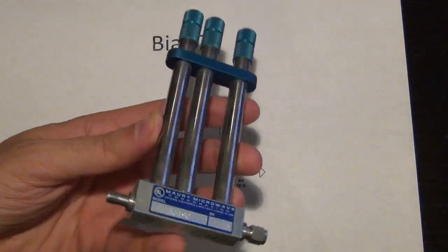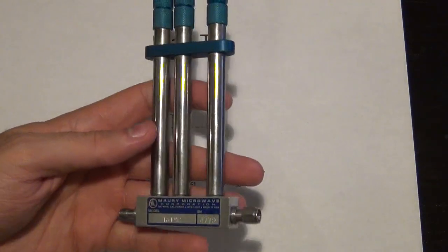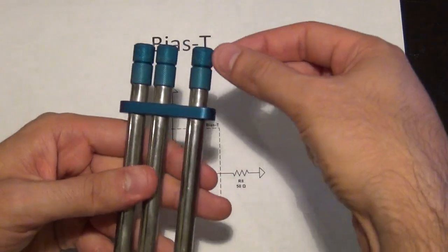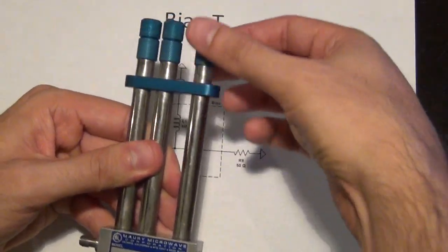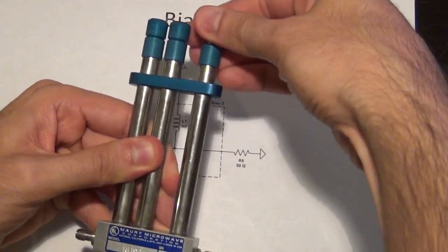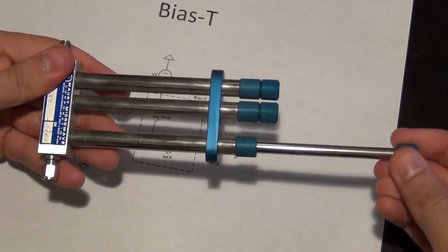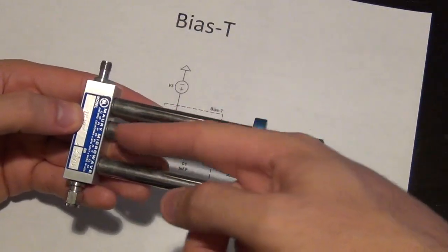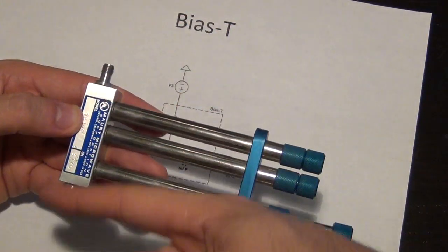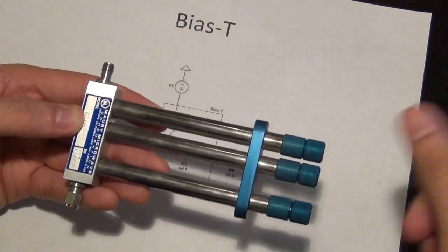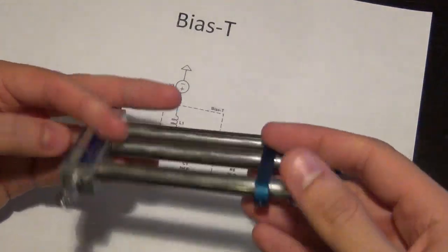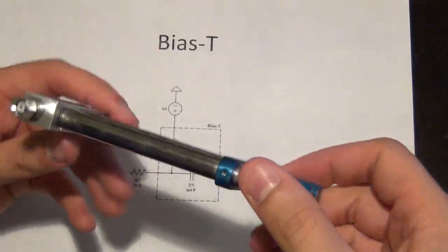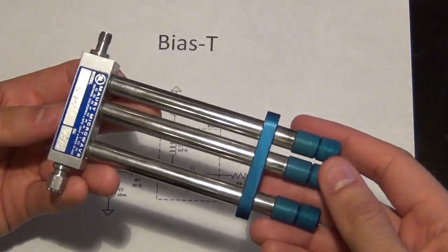Here's an example of something else that you can do passively. This is a tuner. If you have this, again, I will do another video on these type of things later, but by adjusting the distance between the conductor in these rods, these are like stubs, and you can actually change the characteristic impedance. You can see these things extend in and out, and by doing so, you can actually tune a certain characteristic impedance in here. So the signal that flows through here and goes out of there will see these stubs along the way, and you can create a certain frequency response or an impedance response that you want. There's a lot of different things you can do with this, but I thought it would be cool to show you that you can create that classic stub behavior by using a component like this.